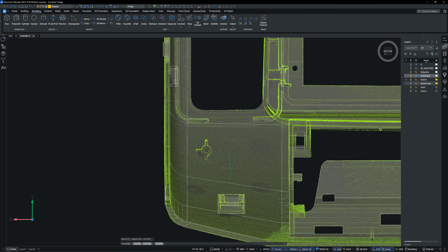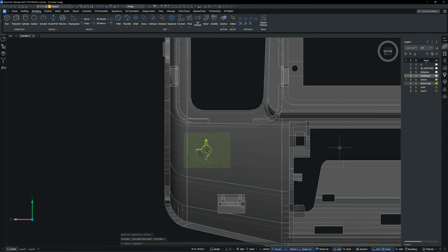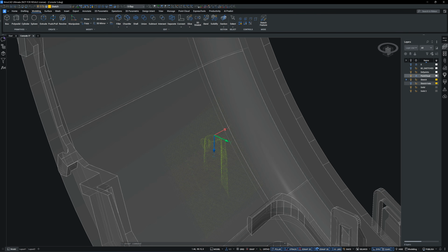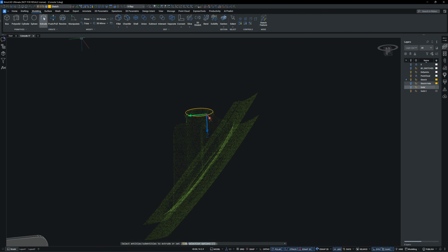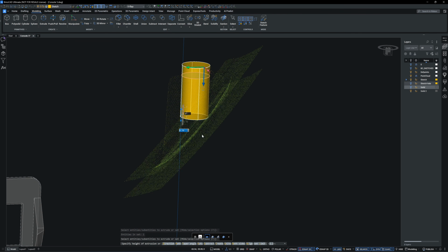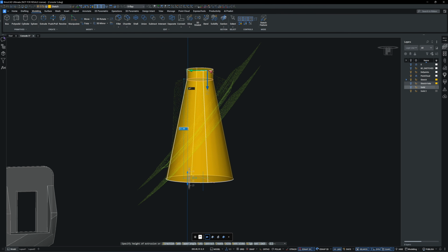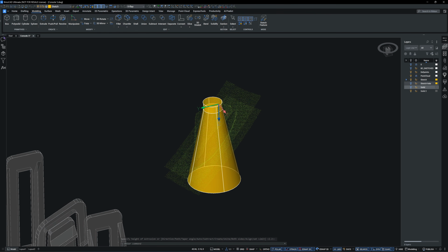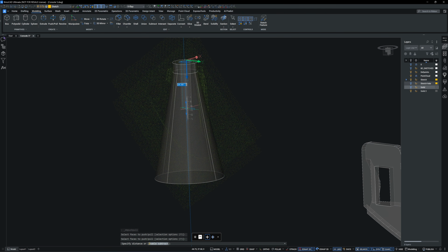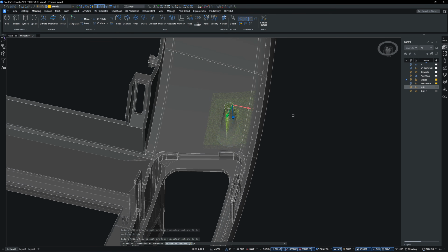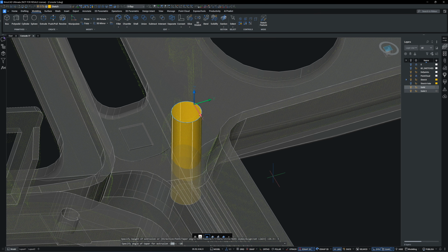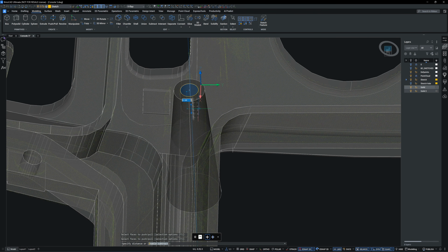I use UCS view to align the XY plane for the screw mounting hole sketch. Then UCS move to snap the point cloud onto the top mounting face. The solid above the stiffener has to be clear to match the scan data, while the solid below can be tapered for strength. I taper the cylinder by 5 degrees and ignore the thin stiffener. Those are meant for injection mold parts. For FDM printing, we can print hollow, so I will use the tapered cylinder instead.